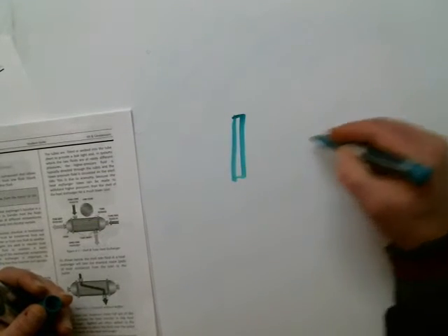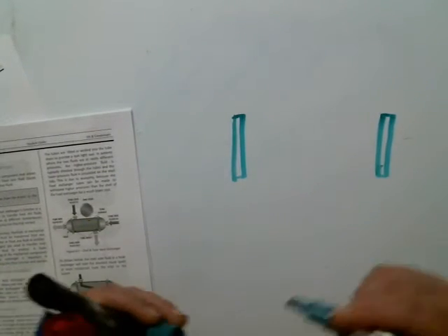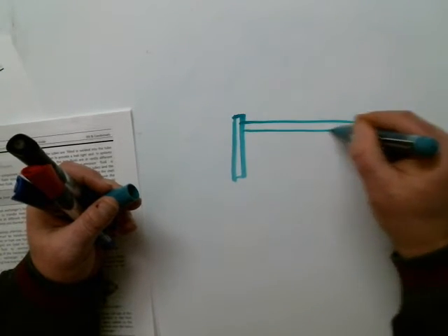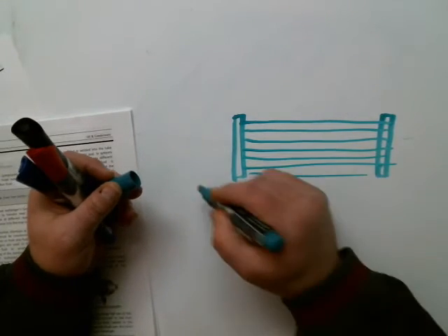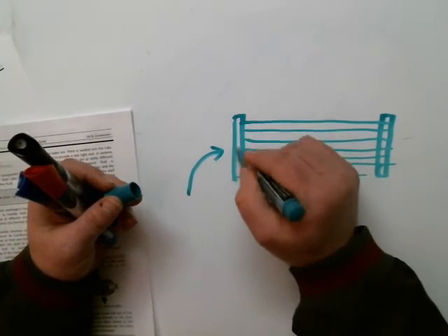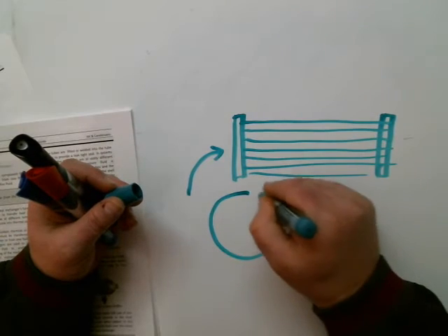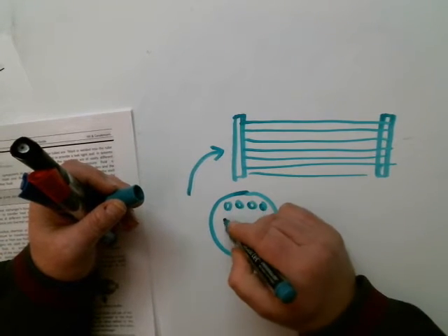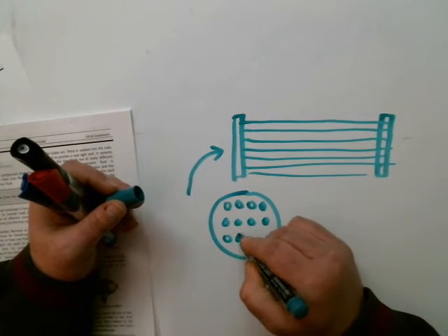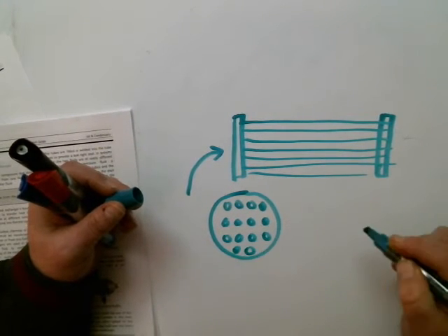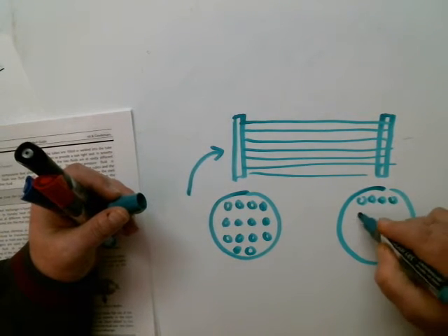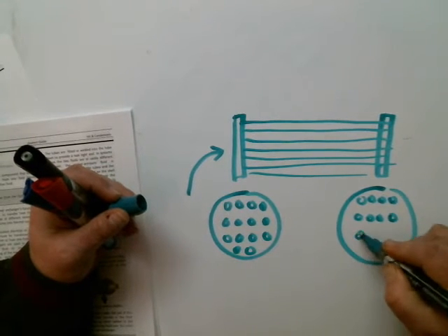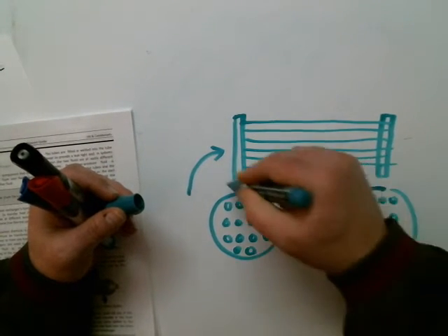If we were to look at it, here is a tube sheet, and I haven't even shown the shell yet, and it's got all the tubes in it. These are the tubes, and then the water is going to come in, and if I looked at the end of this, it would have holes where the tubes are on each end. So water can go through the tubes, and this end too has the same exact holes. So water, or whatever fluid it is, could flow through the tubes.